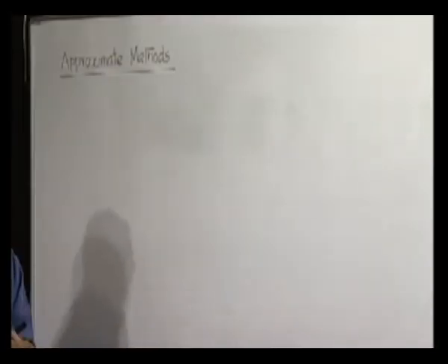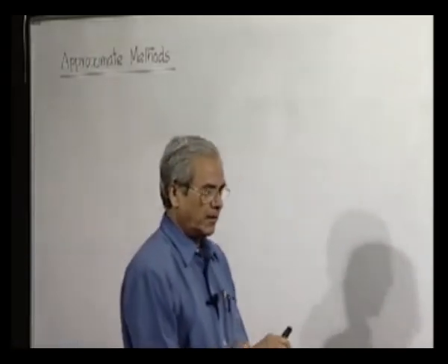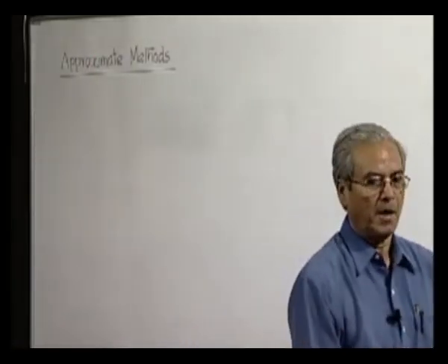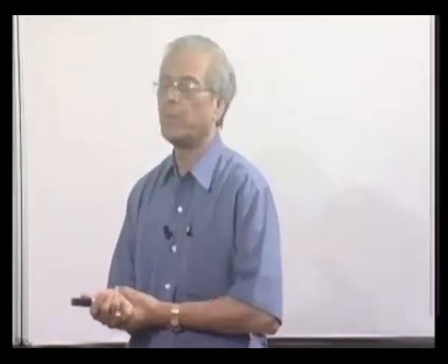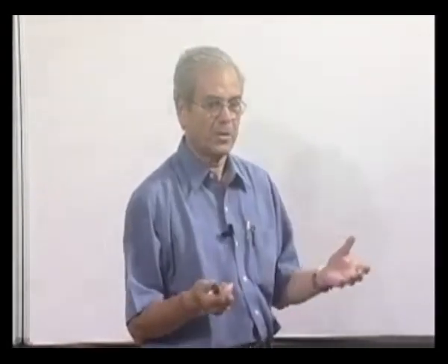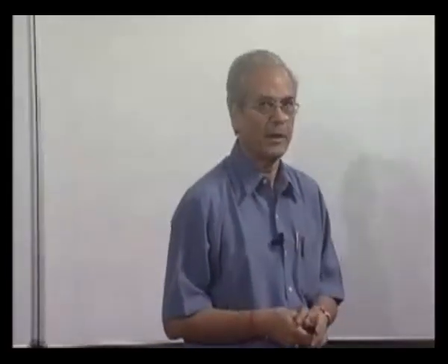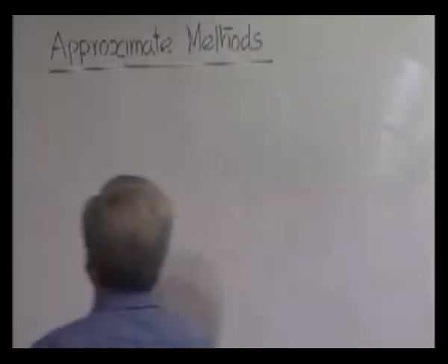The approximate method we have discussed in the case of lump parameter system can be extended to continuous bodies also, because continuous bodies can be considered to be lump parameter systems with infinite degrees of freedom. So one of the most prominent methods which we have discussed, we will apply here by slightly modifying that method suitable for continuous body, and there we come to our Rayleigh approach.